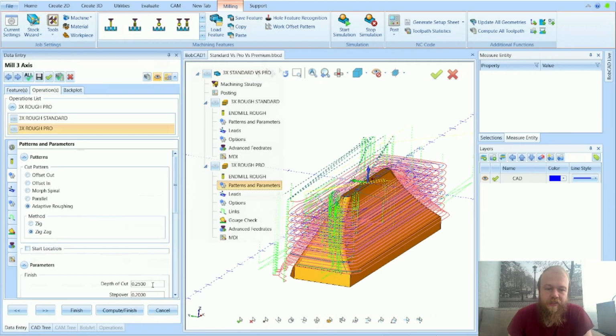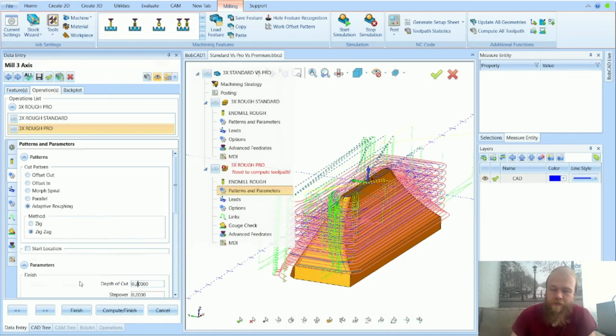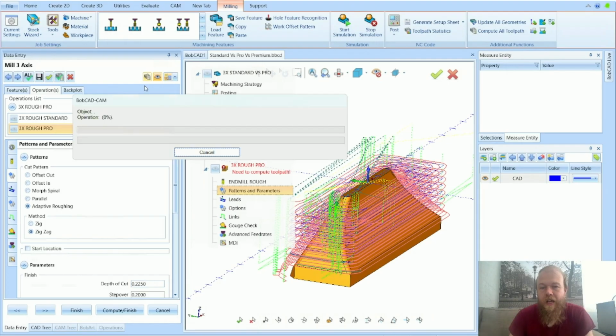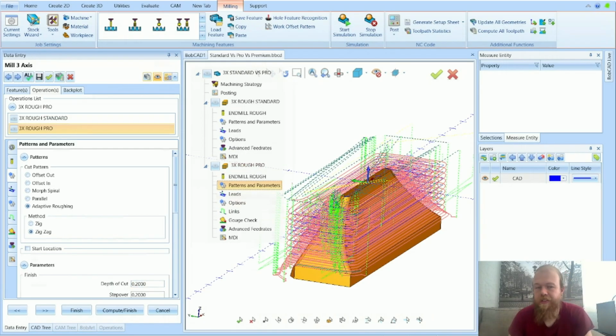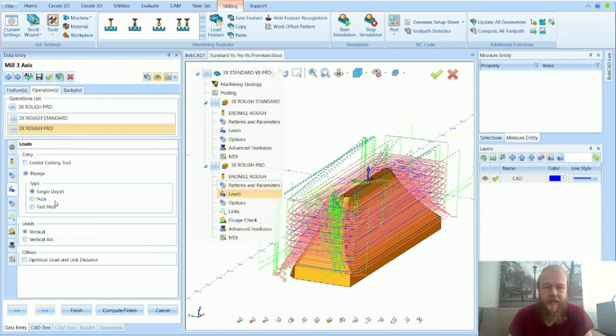Now you can easily, let's change the depth of cut to 225. Hit compute up at the top, it updates for me. Yeah, that doesn't look good. Let's do a depth of cut of 200. So now I can change it to 200. Hit compute. Okay, that looks fine. And then I can go on to the next page and change those settings. Click compute, so it'll compute in real time for us, so we don't have to close out of the cam wizard here, look at the toolpath, go back into it every time. Saves you time that way.